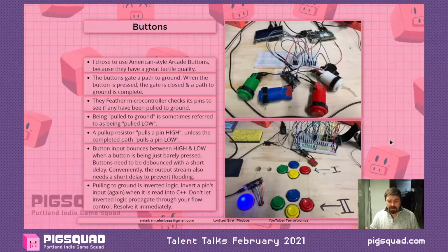The logic's going to come in inverted because it's pulling low, so as soon as you get it in, flip it. You don't want inverted logic going throughout your system. Just clean it up before you move on. Save yourself a headache.